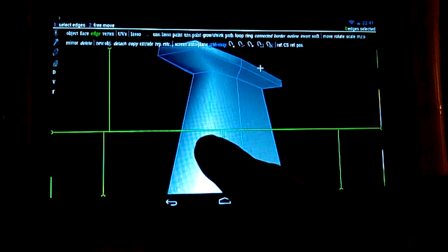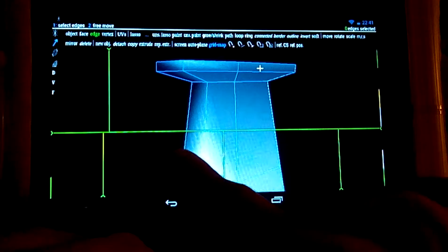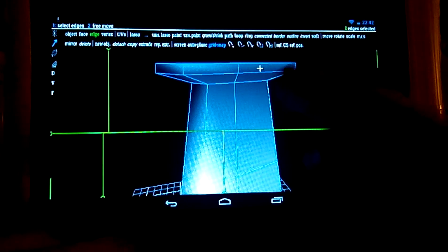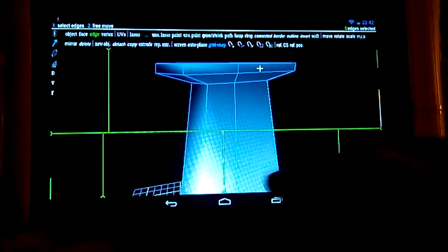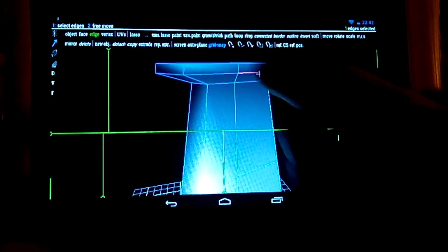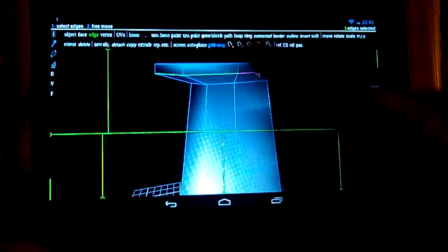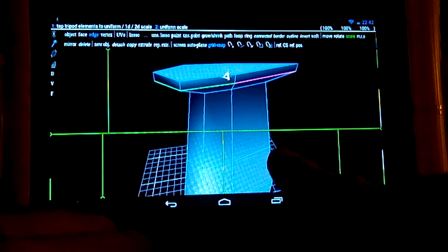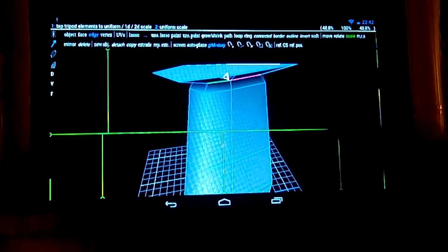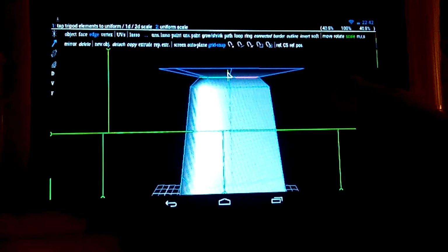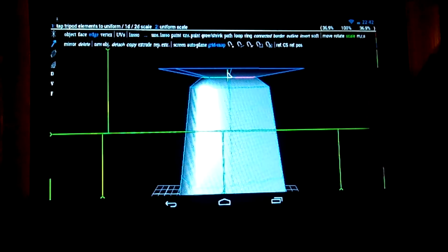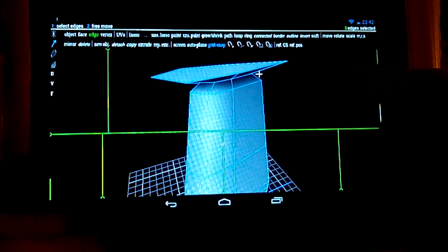Now I'm about to taper the wing tip. No, sorry, not to taper, but to round it. It's better to have at least 4 subdivisions, or 5 if the wingtip is really rounded, but in this case, just to make an example, I selected this one. So even in this case it's better to have measures and not to go just by instinct. Let's say for example, yes, like this. And last,